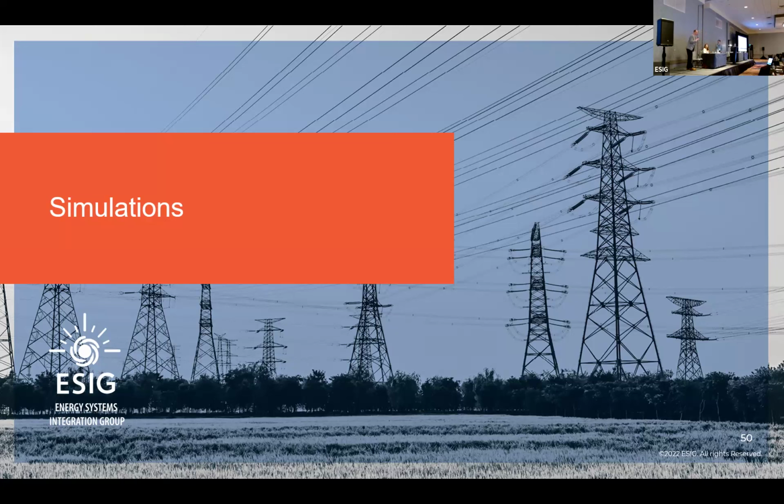I guess I'd share on the updates. When would you update the model for a synchronous plant? Out of cycle, a generator rewind or an excitation system upgrade. I mean, months-long processes, cabinets moving, big physical hardware. And even then, I'd argue performance is not going to be wildly different. But with IBR now, it's just a different animal.